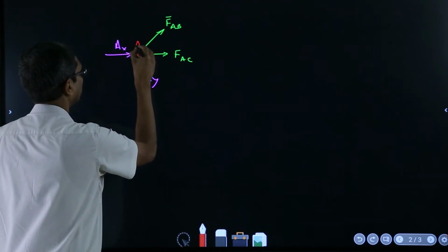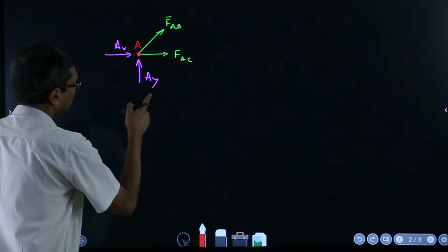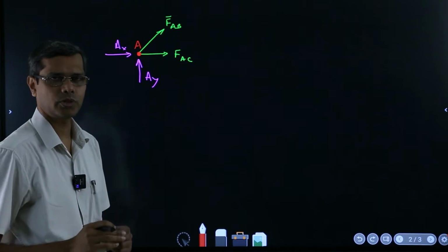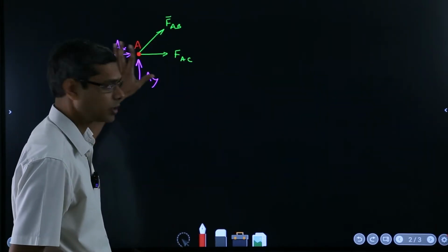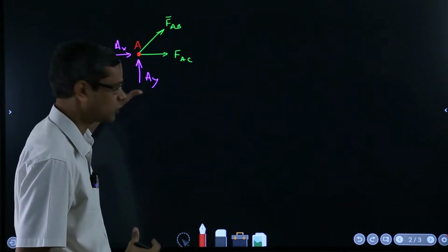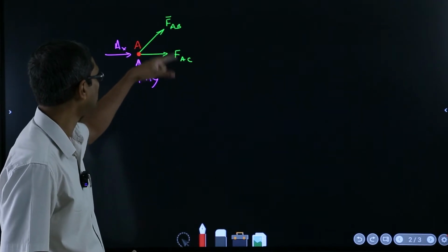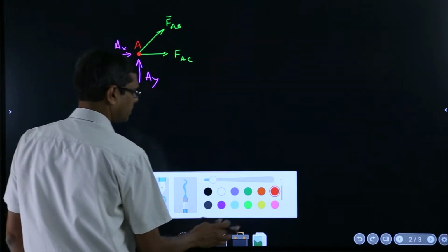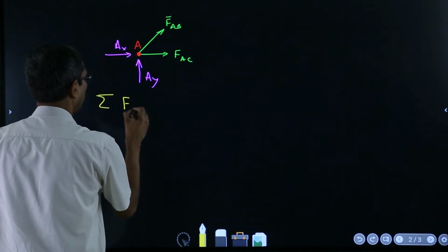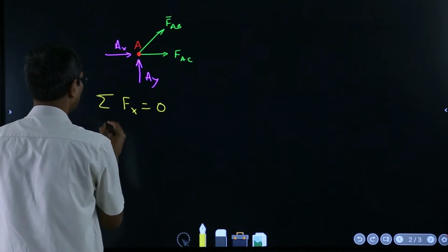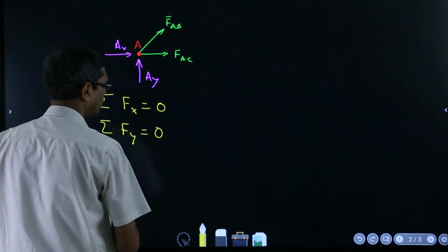The joint A. So we are writing the equations of equilibrium of A. Now if you pick the joint A to start with, you are done, because there are maximum 2 unknowns, and I am now assuming that you have already figured out what AX and AY are. That means only 2 unknowns, and you can write 2 equations which are Fx equal to 0, the summation of all x direction forces, and similarly Fy equal to 0.